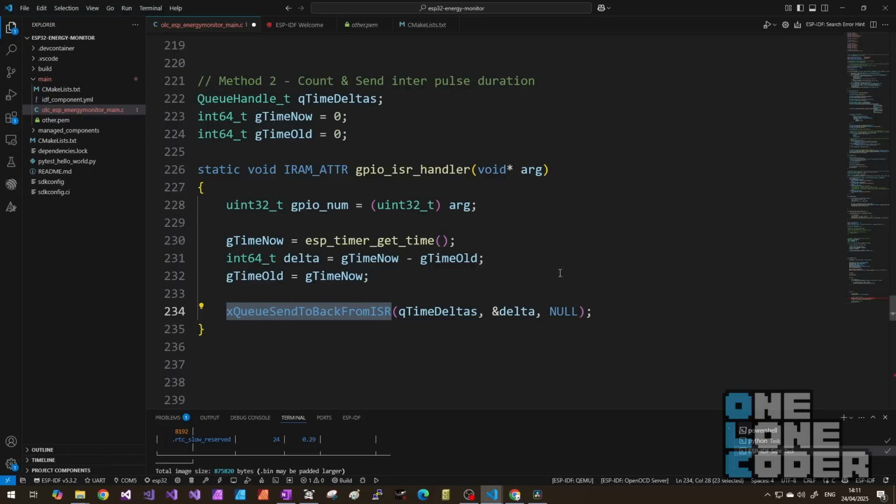It's important to queue this value from the interrupt service routine. The last thing I want to do is go and get the WebSocket trying to do some communications during the interrupt service routine. I was always taught that an interrupt service routine handler should exit as quickly as possible. They're typically considered very high priority and will block everything else from happening. Fortunately, the ESP32 library provides some functions for thread-safe queue handling from interrupt service routines, and that's exactly what I'm using here as I deposit the delta into the queue.